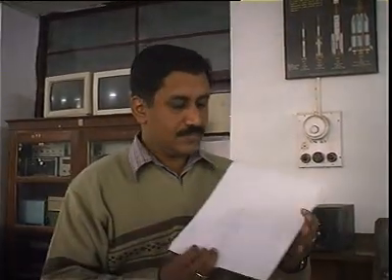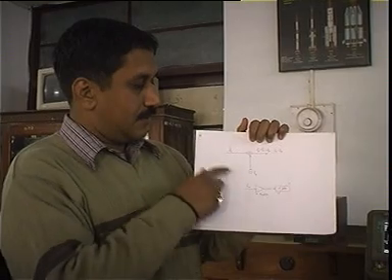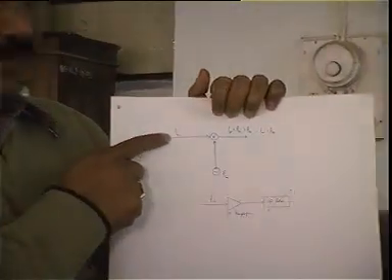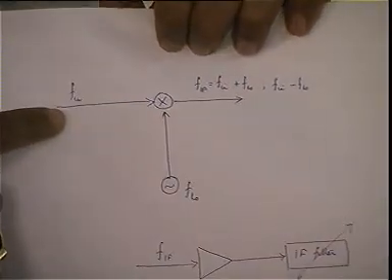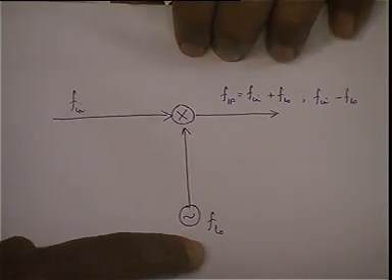The third important factor of a spectrum analyzer is the resolution bandwidth. Now what do I mean by resolution bandwidth? First, to understand this, let us understand what is meant by the principle of heterodyne. I have a small diagram here. You see, here is F in, that is the input signal, and this is a local oscillator which is present inside the system.